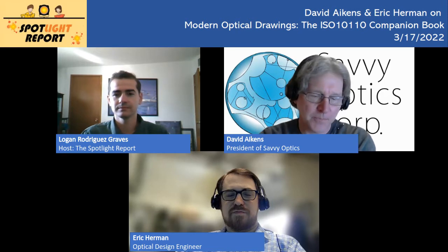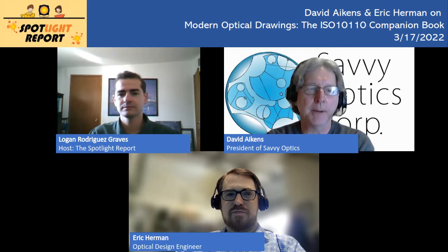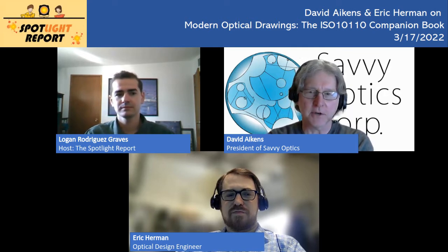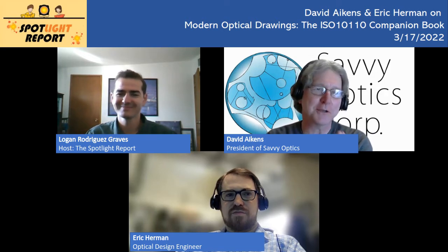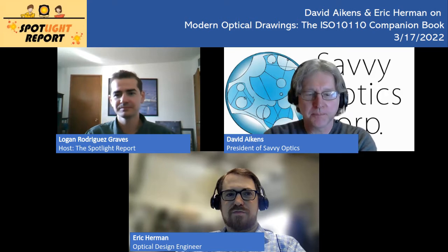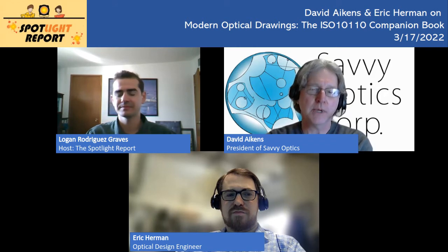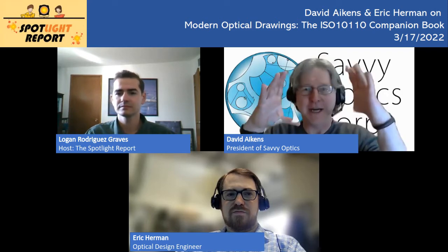That's a great question. It really does come over time. There's no question that experience is the best teacher here. I had some specific events that occurred in my life that taught me an enormous amount about tolerances, especially tight tolerances. And if I can tell you a little story, I was a young consulting engineer working for an aerospace company in the Pacific Northwest. And I had designed a new FLIR system, so long wave infrared. And I remember the primary mirror was specified to 0.005 of an inch on centering tolerance for the objective lens, right? So this is like an 8-inch diameter lens.